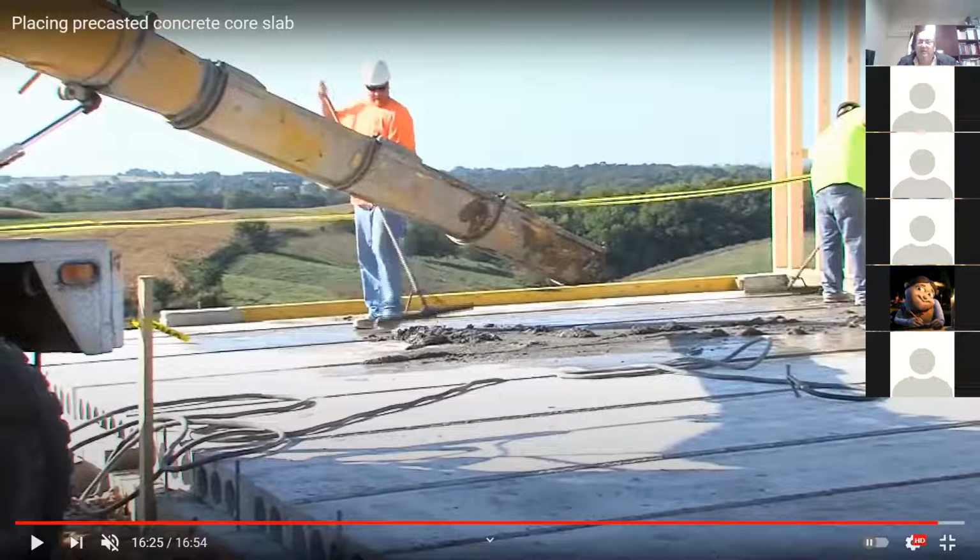Okay, how come they call it post tension? They put the cable through a conduit, like electric conduit, a hollow pipe. But it's not that big, not like 2 inches. It's slightly larger than the cable size. And then they pour the concrete around it. Now the concrete is outside of the conduit, right? There is no direct contact between the concrete and the tendon or the cable.